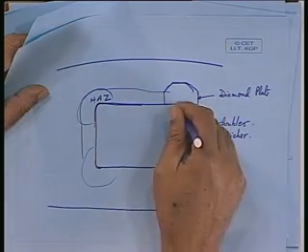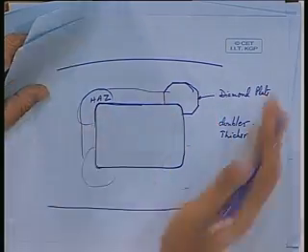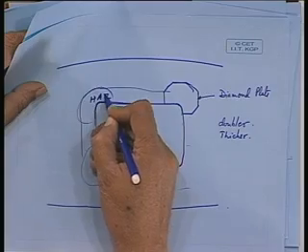So, basically at the same place you are heating at least 4 times and cooling it 4 times. And I do not know whether any cooling rate or heating rate was properly controlled or not. Even if it is controlled, what is the effect of it? So, one has worked over this HAZ multiple times.